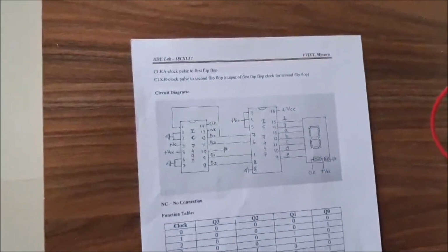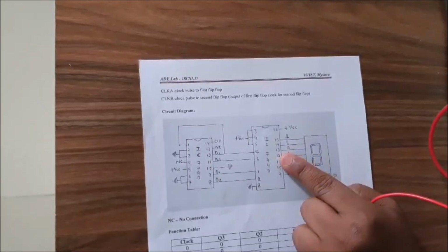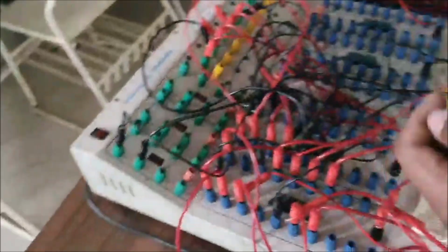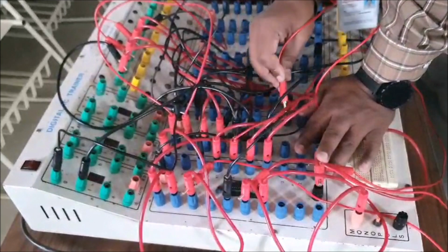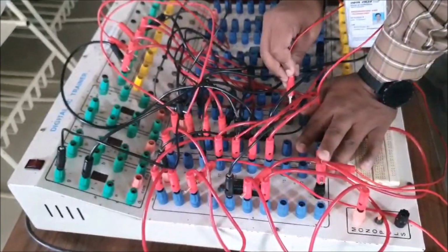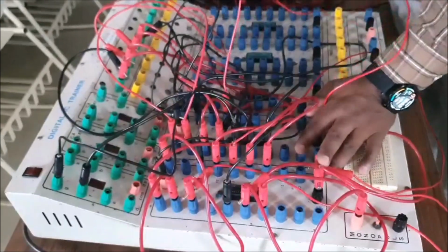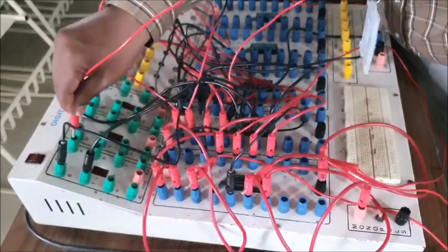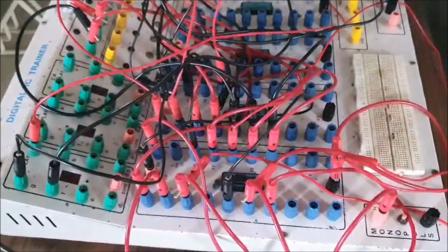Next is A. So 13th pin is connected to the A input of 7 segment display. I will take one patch cord. One end is connected to the 13th pin of 7447. So from the bottom right corner, pin number starts from 9, 10, 11, 12 and 13. I will connect one end to the 13th pin. Another end is connected to the A pin of 7 segment display.